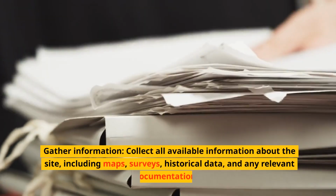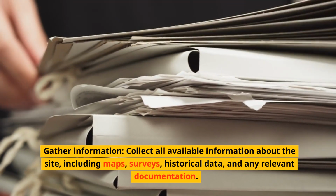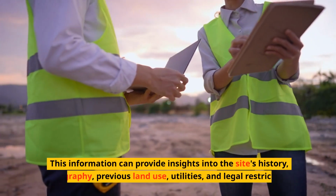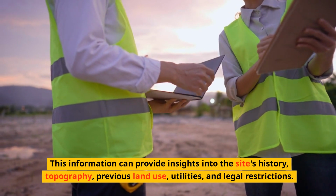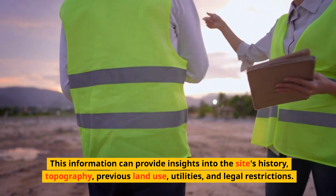Gather information. Collect all available information about the site, including maps, surveys, historical data, and any relevant documentation. This information can provide insights into the site's history, topography, previous land use, utilities, and legal restrictions.